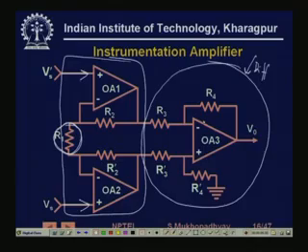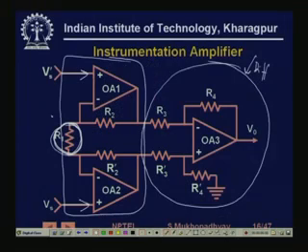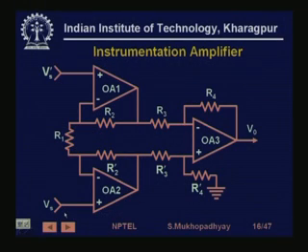If you want to program the gain, you program this resistor, either by connecting jumpers or by connecting external elements. So this is an instrumentation amplifier, and the gain will be the product of these, obviously. So you can learn more about it.